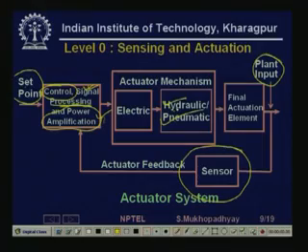There are certain advantages, especially that hydraulics can handle a lot of power in a small volume. So in a small hydraulic motor you can handle a lot of power. When we have large power devices we use hydraulic and pneumatic. They are also like power amplifiers, only they take an electric signal. So typically you have electro-hydraulic or electro-pneumatic actuators. Finally, at this point you have generated the necessary process input which you wanted to cause, with a lot of power.